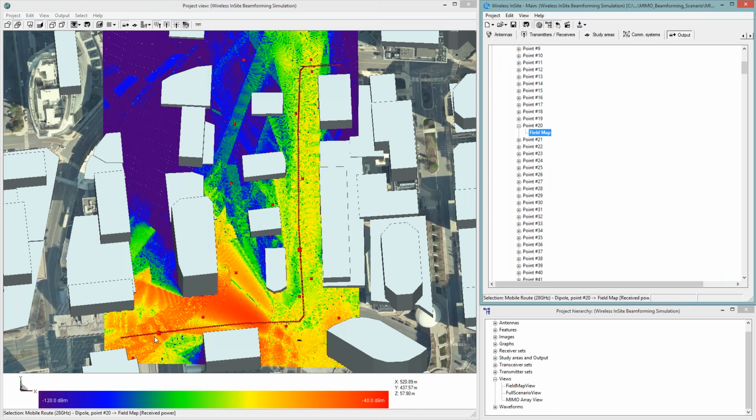and when we applied our beamforming techniques, we can see a slight shift in how the power is being directed. This isn't a perfect singular beam. We actually have some different lobes. A very strong lobe is reflecting off the side of a building and making its way to our receiver point. There's another lobe that is coming along the side of this blocking building. And there are also other side lobes that go down other streets and down the main street in front of the array. But we can clearly see quite a change over the previous field map showing how the energy has been redirected toward this device.